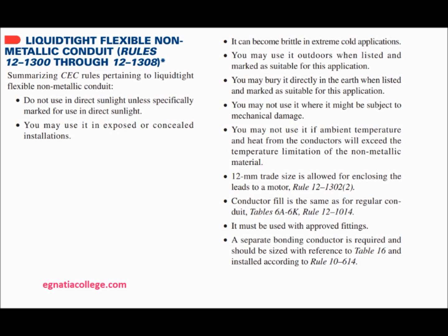You may not use it where it might be subject to mechanical damage. You may not use it if ambient temperature and heat from the conductors will exceed the temperature limitation of the non-metallic material. 12 mm trade size is allowed for enclosing the leads to a motor, Rule 12-1302(2). Conductor fill is the same as for regular conduit, Tables 6A-6K, Rule 12-1014. It must be used with approved fittings. A separate bonding conductor is required and should be sized with reference to Table 16 and installed according to Rule 10-614.